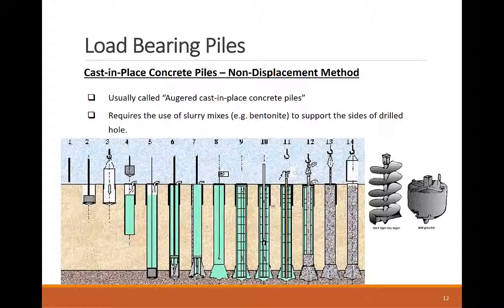While progressing with the concrete pour, the concrete pipe is raised incrementally to be just below the poured concrete in the bottom. This is critical to make sure that the concrete doesn't segregate if done directly into the bentonite slurry mix. Once the concrete casting is done, the top casing is removed. Usually the pile head is jackhammered and demolished to bring the pile top to the desired foundation level.